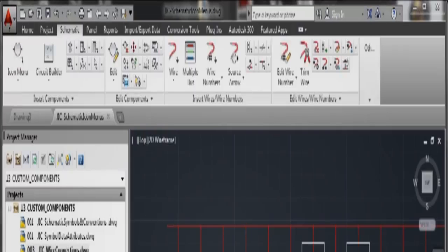When we're working in AutoCAD Electrical, the majority of the time you'll be working on either panel drawings or schematic drawings. When you're working on a schematic drawing, you will be using the schematic icon menus most of the time because you'll be using standardized blocks that have been created for your particular standard, whether that be JIC, Imperial American, or IEC, European Metric.